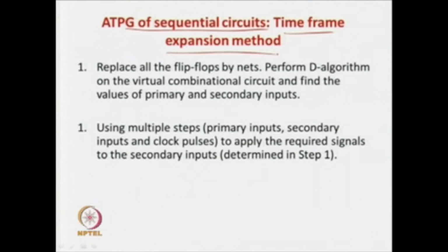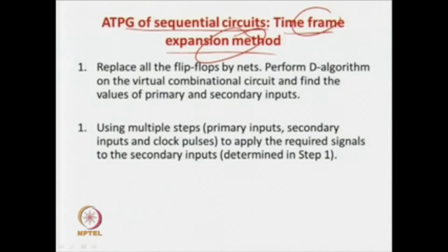Now we are going to see ATPG for sequential circuits using the time frame expansion method, like the D algorithm we have seen. In the D algorithm, what was the idea? That is a formal algorithm to find the test pattern for a combinational circuit. This time frame expansion method is another very formal method, like the D algorithm, which can find test patterns for a sequential circuit. Let us see this in detail with an example.